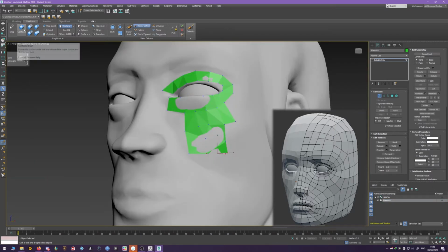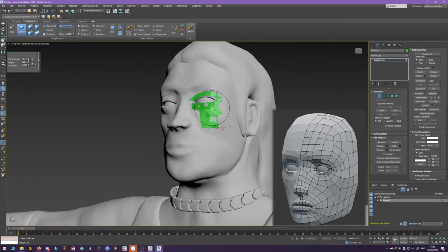The next tool is the conform brush. Relax, soften, and conform should be used in combination. What this means is, when you relax and your polygons go through the mesh, you want to then use the conform brush to bump them back up, and they'll attach to the offset you set. So make sure the offset for the conform brush is the same as the offset for your surface. Now as you can see, as you use the conform brush, it just realigns the polygons onto the surface.